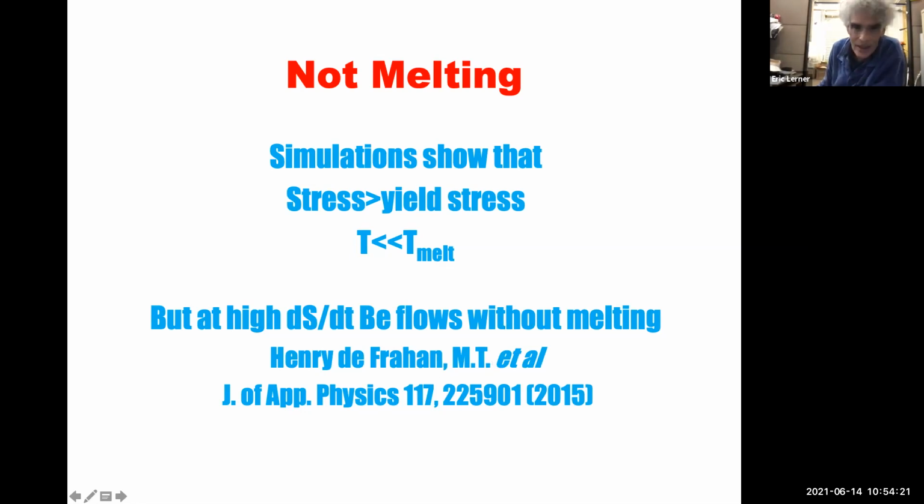But I found in the literature very interesting experiments, which were confirmed by other researchers. Beryllium is fairly brittle. If you bend it slowly, it bends. If you hit it hard, it breaks. Well, it turns out if you hit it really hard, if you have an extremely high rate of increase of strain, it loses its strength entirely.